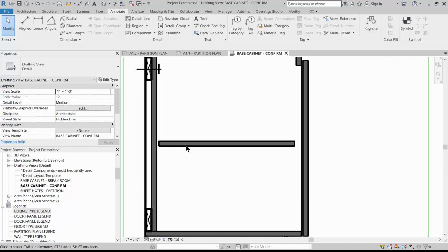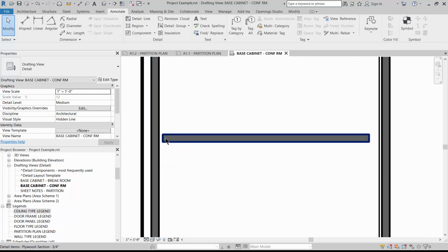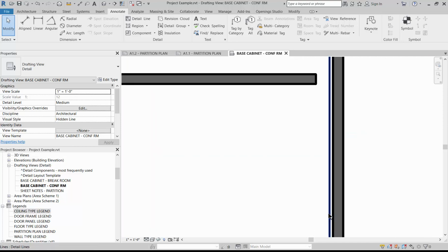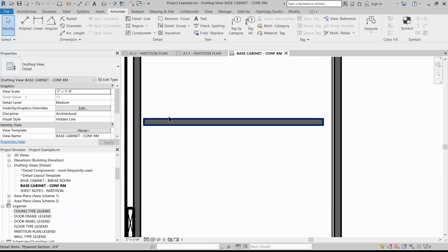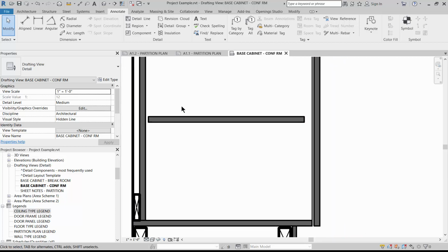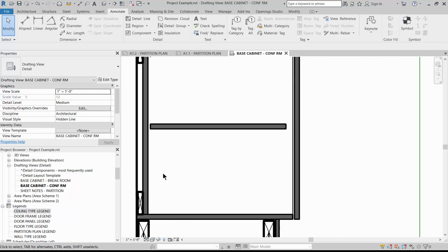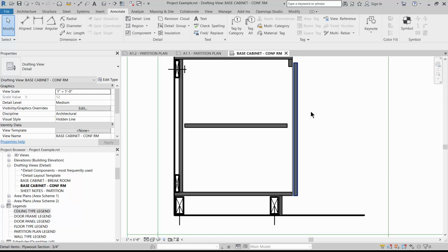I'm showing a shelf, so make sure, again, the lines are set back. This is the face of the cab, this is the actual face of the door, so we're showing all of the layers, and we overemphasize it in details. And I might have a line of dots or little circles here showing that this is an adjustable shelf, and I could also use some detail lines to draw my door handle.